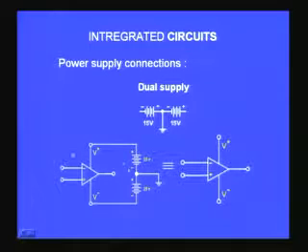I have shown here a very simple picture where the op amp, the symbol is shown here, is connected to V plus and V minus, which are now connected to 2 batteries in the way I showed you here, and the center point is maintained as the common ground, and you have plus going here and minus going here. This is what we call a dual supply.